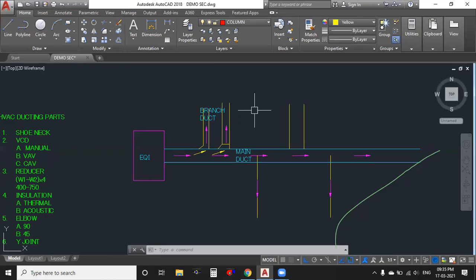Do we get this reference in ASHRAE? Yes, 100% we'll get it. Sir, please mention the code reference as well, which clause we need to refer to, because it will be good for us in a job interview. Yes, sure. So when it's below 600 mm, 100 mm, and when it's above 600 mm, 150 mm, right? Thank you.